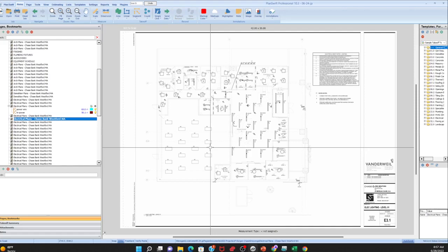So when we measured the home run as an entity, if it's 100 feet, even 1,000 feet, whatever, what we really meant was 100 feet of the conduit, but inside that conduit is 3 times that 100 feet, because that's how we run home runs. It's 3 of them, or 4 of them, or whatever it tells us. So however many triangles are on there. Right. Exactly. Yes.